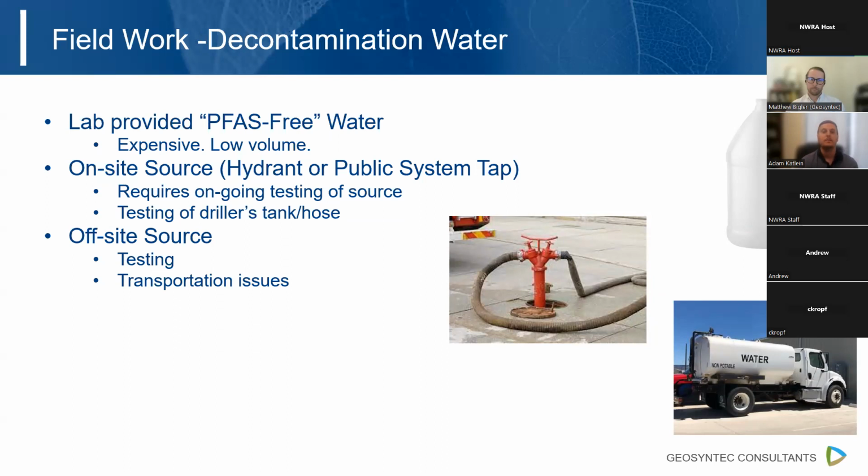If you are using a driller's tank for like soil sampling or things like that, we'd recommend testing of the driller's tanks or hose because it's not going to be clear if they're coming from another site where their water was from or any potential contamination sources that would be available in that. So we would recommend an ongoing testing to make sure that your decon water is good.